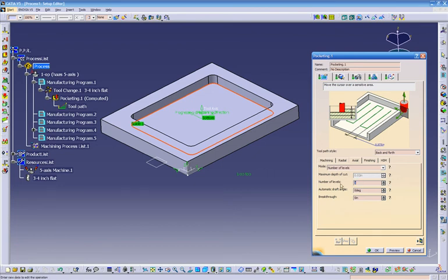So let's say we want to cut this 3 times, and let's make the depth of cut. We cannot select it right now, but if we change this to numbers of levels without the top, because we didn't select the top yet, we just put without the top right here. So now it's gonna tell us, okay, this right here stands for the thickness. So we put 200 over here and 3 times. It's gonna ask us if you want to make any finish passes.